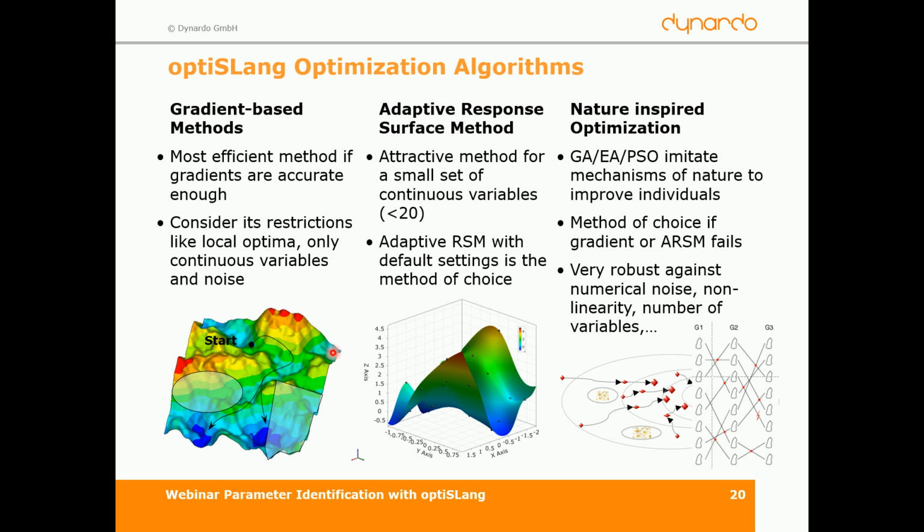And for this, we have a wide range of optimization algorithms like the gradient-based methods. These gradient-based methods have the best accuracy if we can really compute some gradient. But if you have maybe some failed designs or numerical noise, the gradient-based method doesn't work for this. So for this purpose, we can use the RSM. But for some maybe global optimization, the PSO and evolutionary algorithms are quite efficient in order to really detect the regions of global optimum.